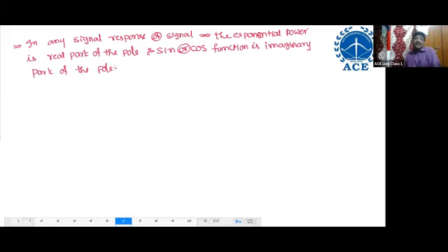Once you get it, the real part gives the time constant, and the imaginary part gives the frequency of oscillation, omega d. In the previous case, what is given? c of t is e power minus 3t sine 4t. Even if it is 1 minus or t minus, whatever it is, the exponential power, take as real part. Sine or cos, you take it as imaginary.